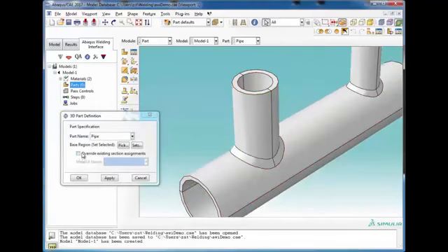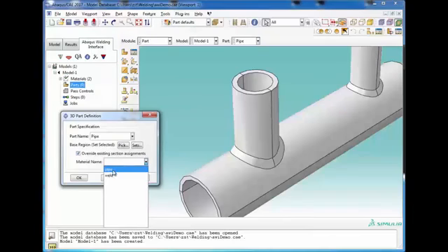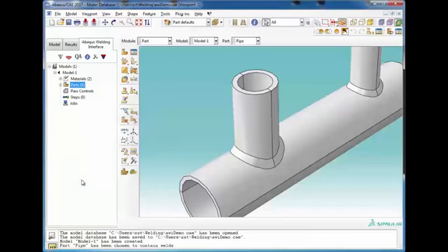All right. And then the other option is if you don't have any section assignments here, and the section assignments are based on the base material and just the welds, then we can just choose to have the AWI fill that in for us. Okay. So you'll notice we still don't have a green check mark, meaning we haven't given the AWI enough information to distinguish what region is what. So we've given it the base material, but now we have to let the AWI know which is the weld materials. So the first thing we're going to do is go through the first step, which is just assigning a mesh,